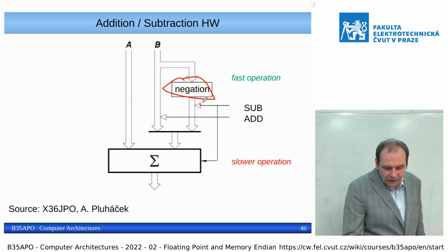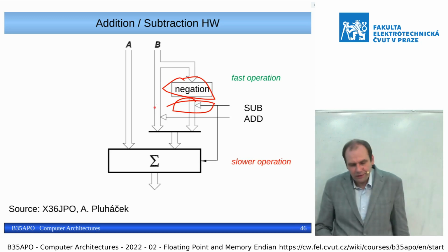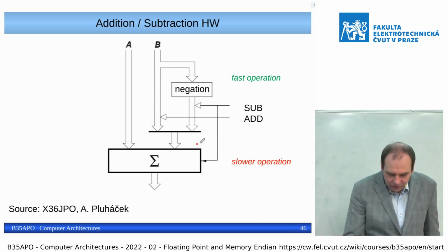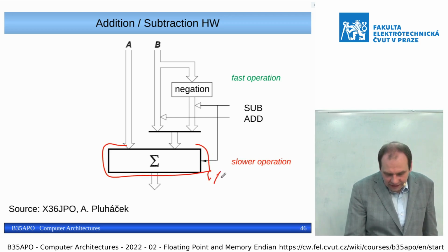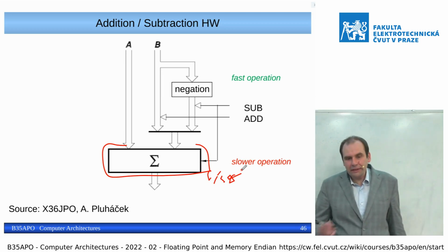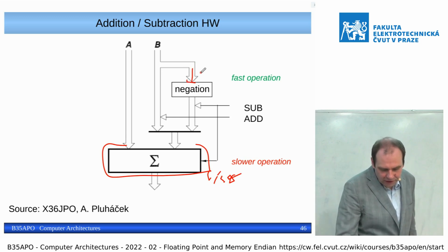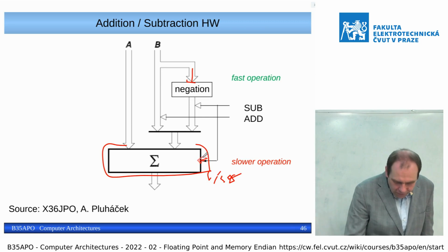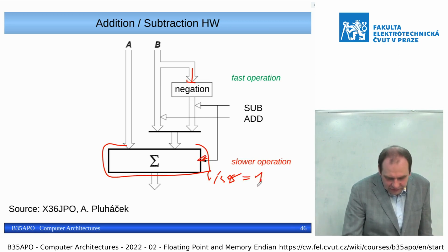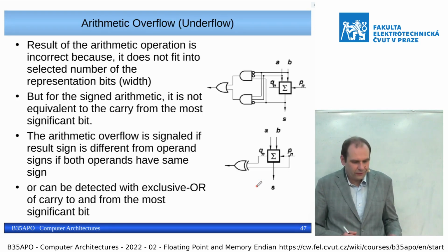But we do not need to add extra logic to add the 1, because for the case when we use the adder anyway, we have there the carry in 0. So if we know that we want to subtract, we negate the bits on the input B, and then we set carry in 0 to a 1. For addition, we do not need to do that.